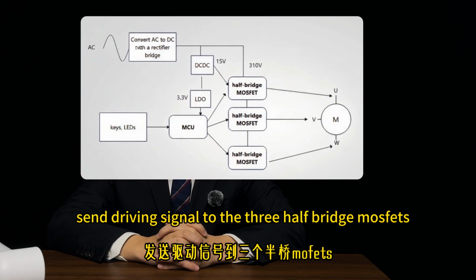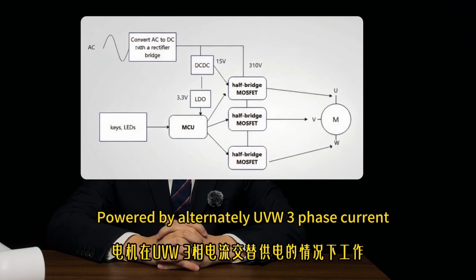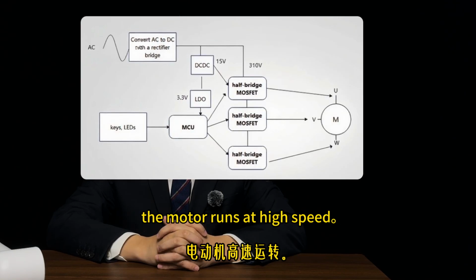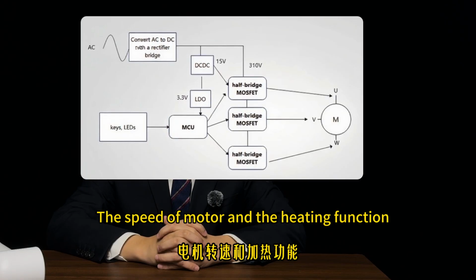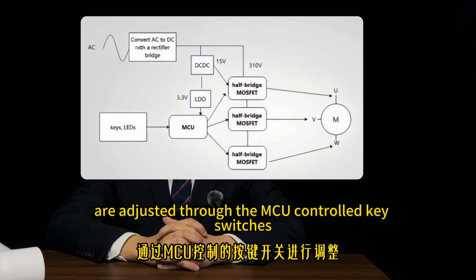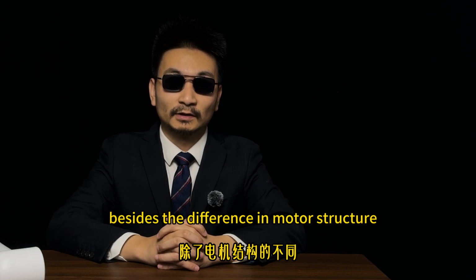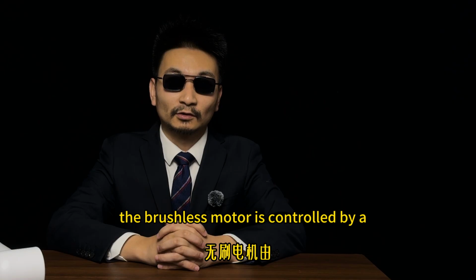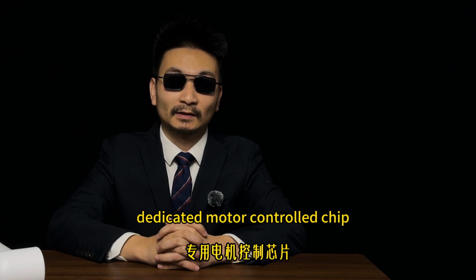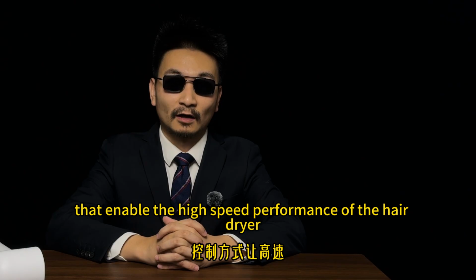The MCU sends the driving signal to the three half-bridge MOSFETs, which are turned on and off alternately, producing UVW three-phase current. The motor runs at high speed. The speed of the motor and the heating function are adjusted through the MCU-controlled key switches. As you can see from the schematic diagram, besides the difference in motor structure, the brushless motor is controlled by a dedicated motor control chip. It is a precisely upgraded control method that enables the high-speed performance of the hair dryer.